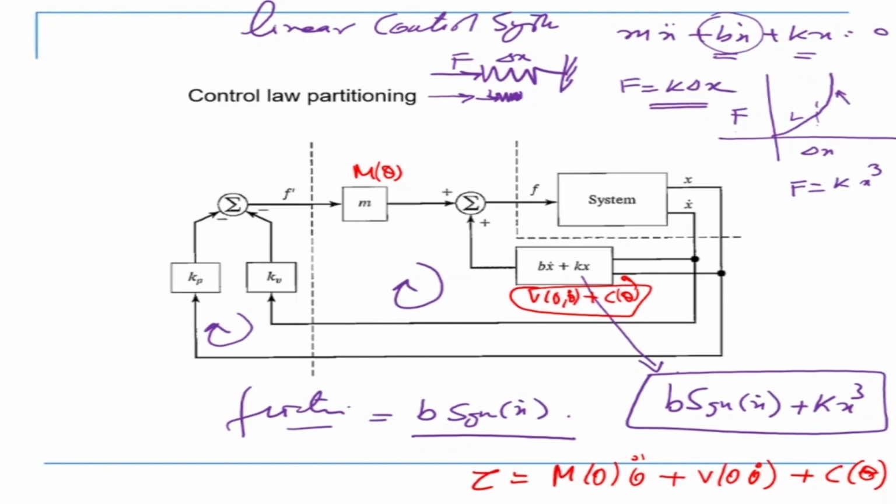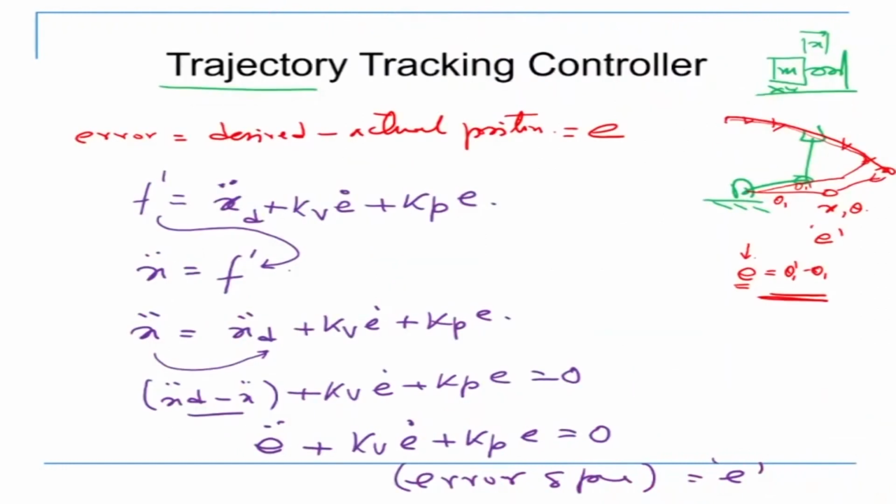The equations are very similar. So I can actually control a robot manipulator for which I know the dynamic equation of motion this way, by putting the model parameters here and the servo parameters there. Although this is a nonlinear control system, we can control it this way because we are dividing it into a model part and a servo part.